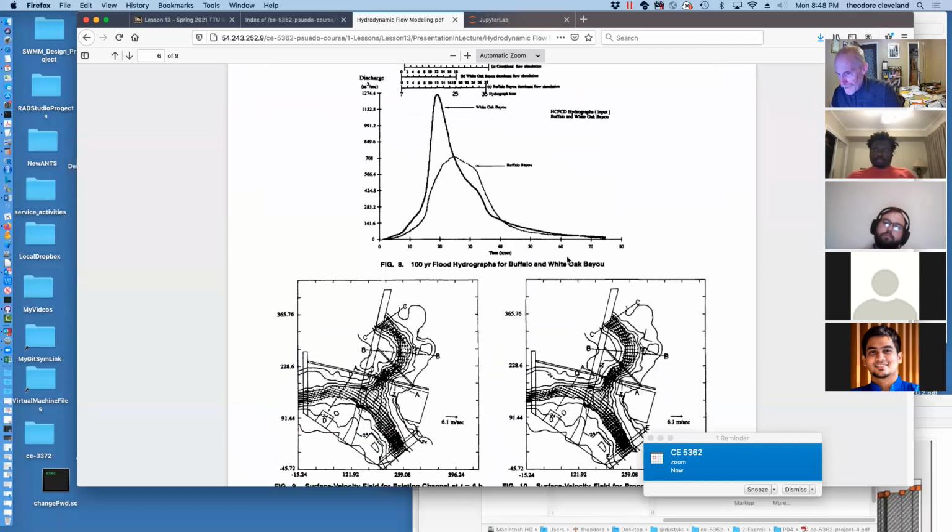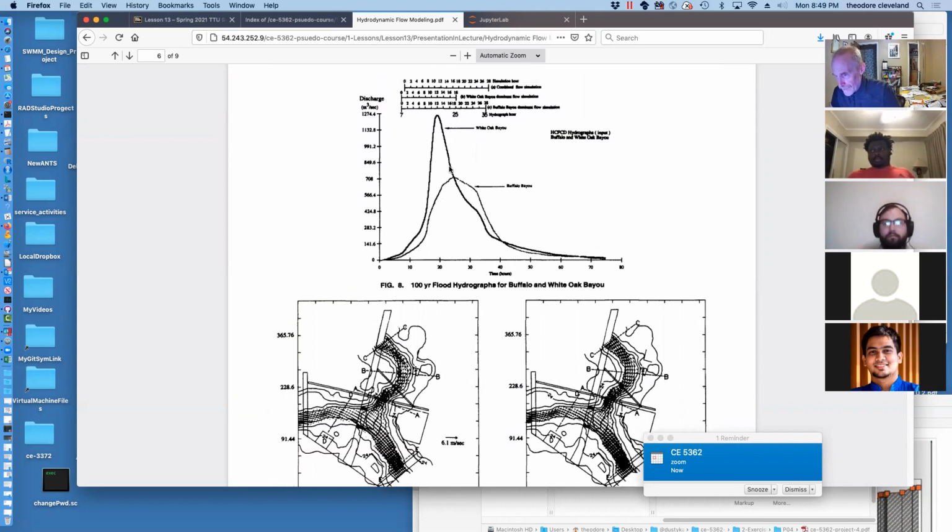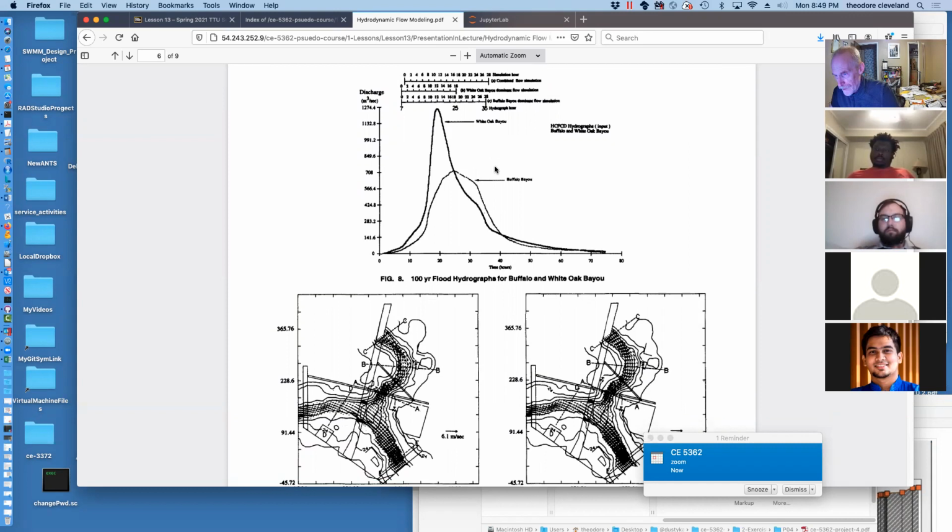And the key thing is that in order to start the multidimensional model, we had to have hydrograph behavior and actually had to run a one-dimensional model to seed things. And so this is quite relevant. Here's the two hydrographs that we're going to examine. And so I can actually get that missing peak from here if I need to. It occurs at around hour 20, and if I remember, the missing peak was between hour 18 and hour 30.